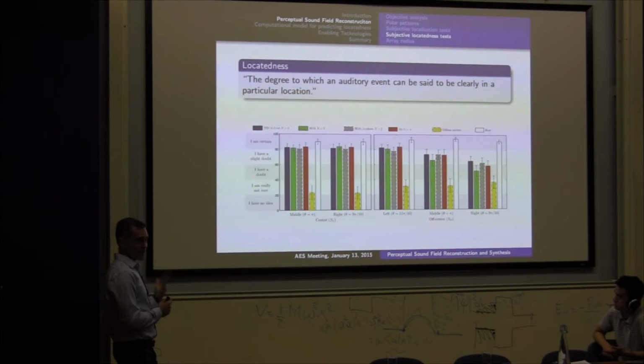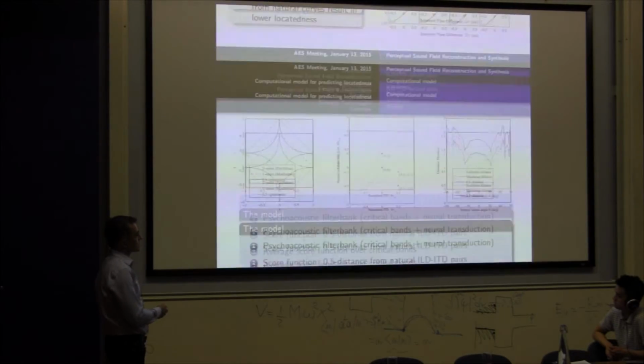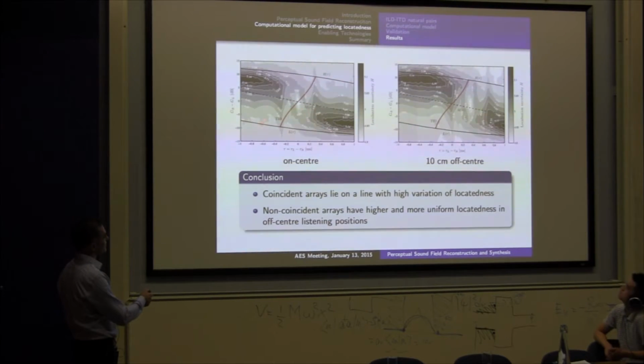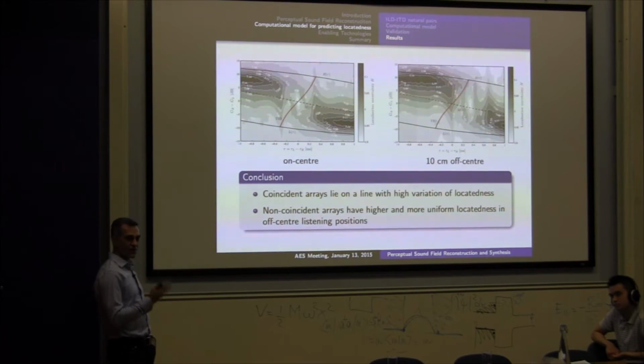There were papers written about all these problems with time intensity stereophony, and they're really known problems. But all that work pertains to really large arrays, like 2 meters or something like that. So where is that point where it breaks, we do not really know yet. But these curves here can provide some guidance. As long as we operate somewhere here, then we are fine. Of course, if you go to a very large microphone array, then it's not good. We do not have a definite answer, but definitely the radius is not that critical.